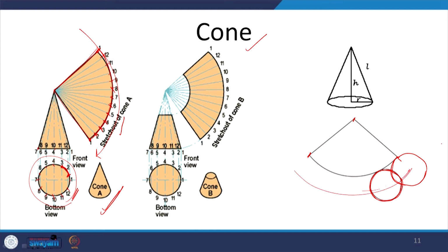So if I just roll this circle along this path such that this point, say A, comes back here as A, I will actually know what is this arc which is going to be formed, which is what we can draw again. So this is equal to the circumference of this, and we will draw a circle at the end of this span of cone here.